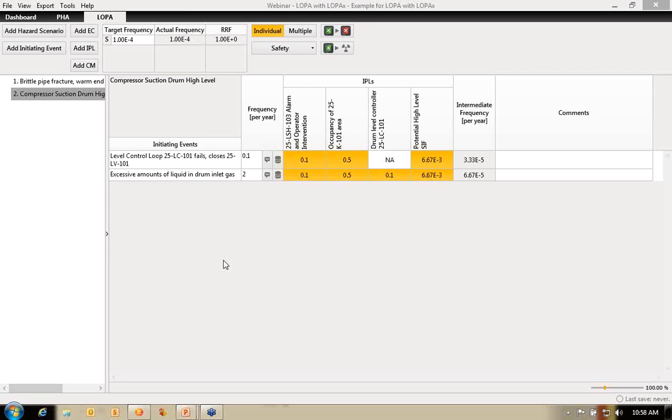And sometimes, I had a scenario where there was a vessel that was not designed to withstand the pressure that could occur within that vessel, and that vessel was next to the break room. In the break room during lunch there could be 10 people, and we came to the conclusion that if that vessel would go, the pressure wave was so high that it would basically knock down the wall in the break room and potentially kill everybody that was having lunch there.